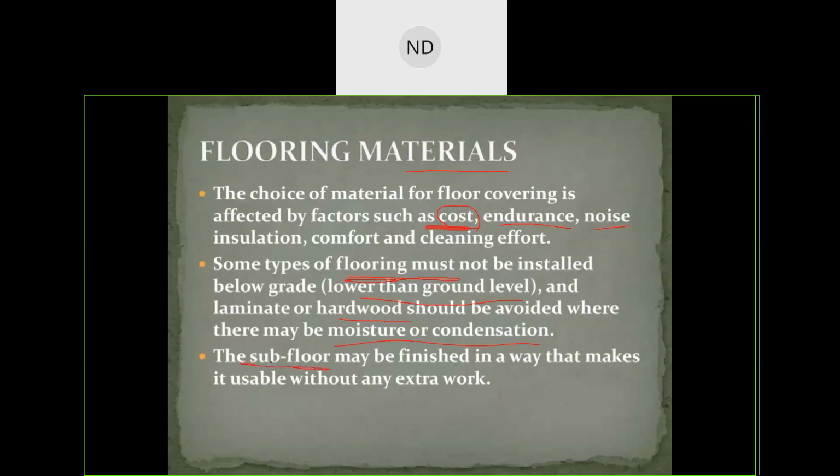For the subfloor you don't need to think of the finishing, that is how good or how bad it is looking. Your subfloor should be strong enough to withstand the walking areas and walking people. It can take the load of the coverings, walking, or any other materials to be shifted. Okay, so that is to be kept in mind.